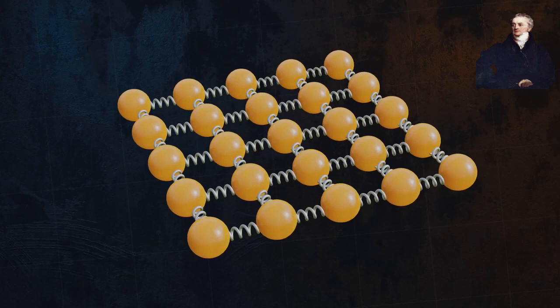Mild steel has a carbon content of up to 0.25%, and high carbon steels can have a carbon content of up to 0.95%. Adding such a small number of additional carbon atoms to the existing iron atoms isn't enough to significantly affect the overall resistance to increasing the spacing between atoms. And so the Young's modulus is very similar for mild steel and for high carbon steel, despite some of their other mechanical properties being very different.